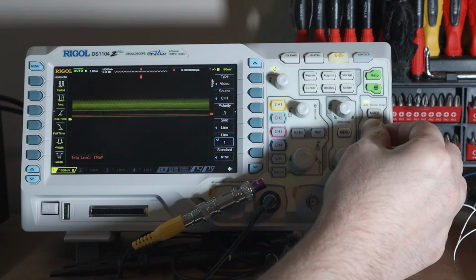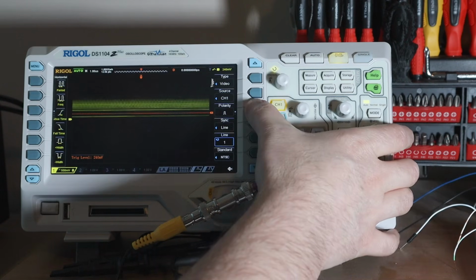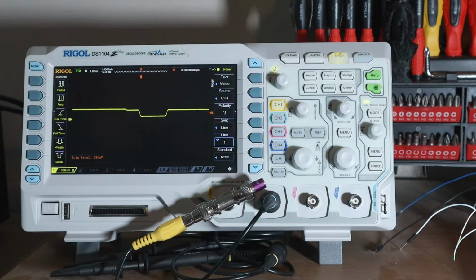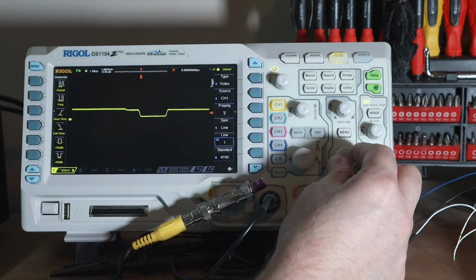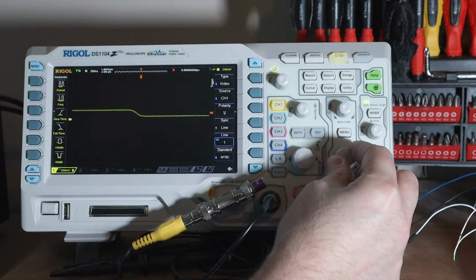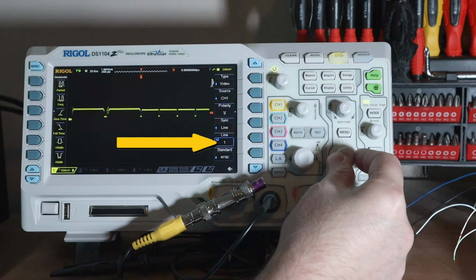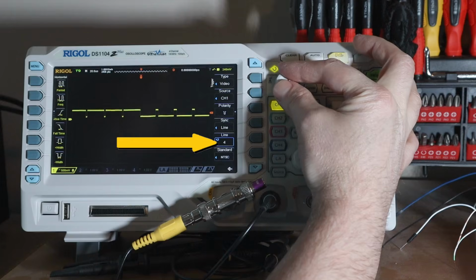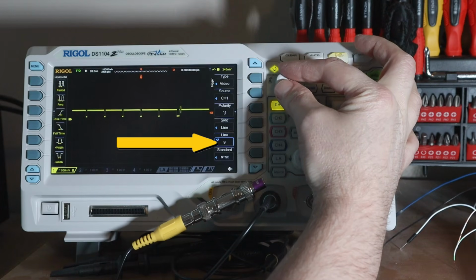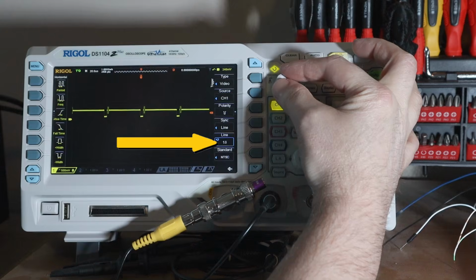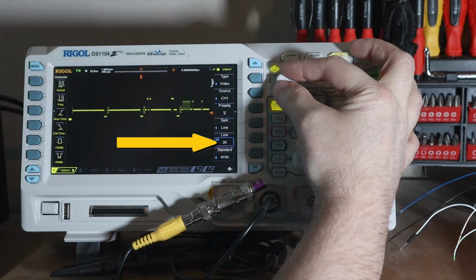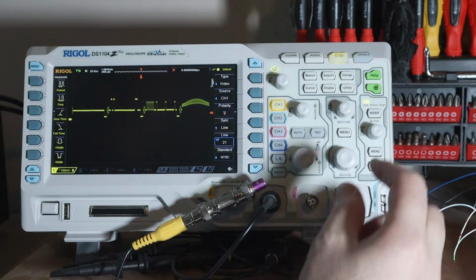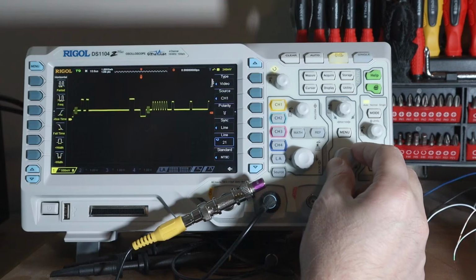I'll move the trigger up, and we need to change the polarity on this scope, which is opposite from the last scope, but you can try the different polarities until one syncs up. We can zoom out a bit here, and look at lines 20 and 21. And now we can poke around the signal and view any portion of it.